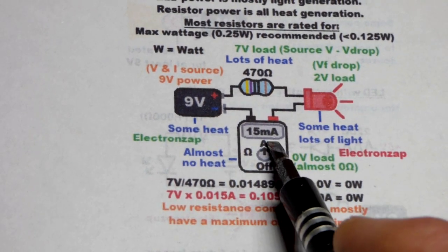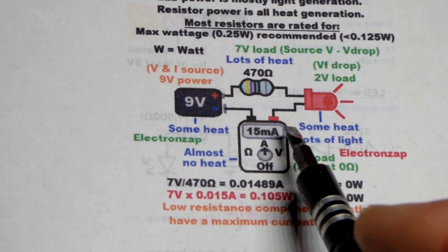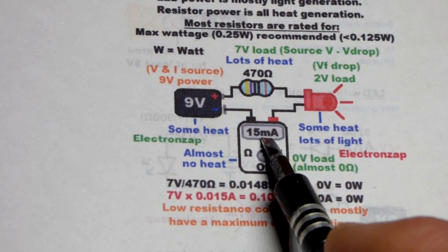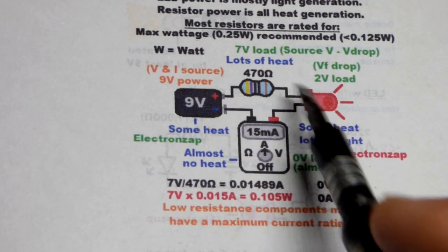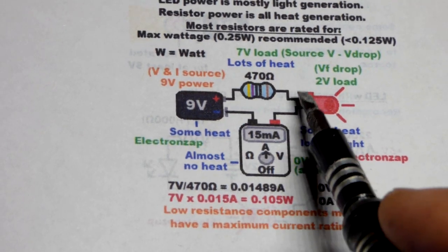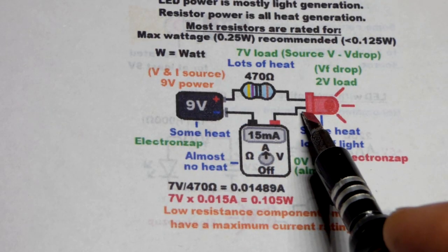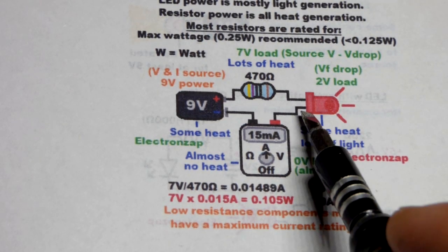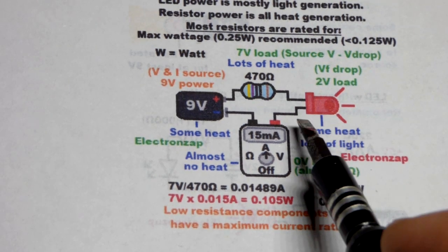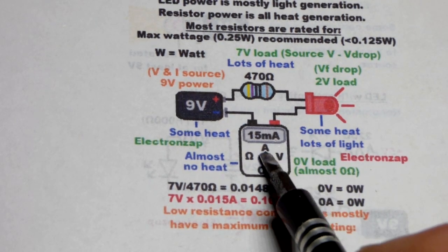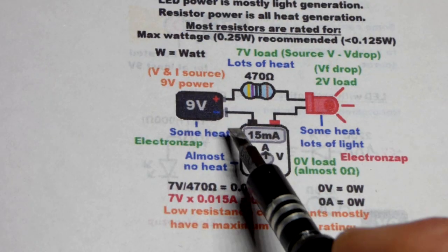So whatever reading you take of a circuit, you want to make sure that reading is close to what the circuit will be providing when the meter is not attached. So when the meter is measuring voltage, it has very high resistance because it does not want any current going through the meter, because then it will lower the voltage at a certain point. Hopefully that makes sense. But when it's measuring current, you want almost no resistance.